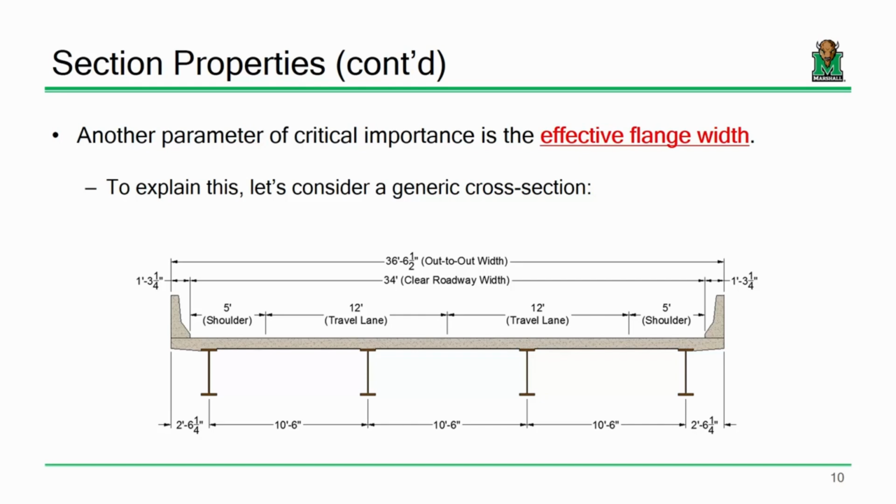Okay. Now, what I want to do when I'm evaluating a given beam, let's say this beam or maybe this beam, if I'm looking at the composite beam, it's the steel plus a portion of the deck. The key word is a portion. For this second beam over, the question I'm trying to answer is how much of that deck is applicable for this given beam? Is it this much? Is it this much? How much of that deck can I consider effective for that beam?